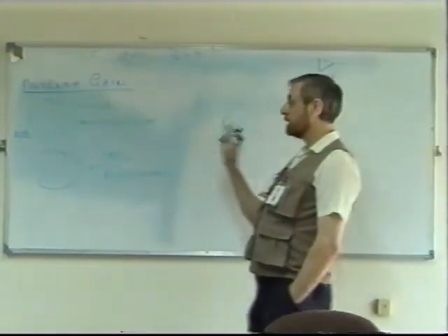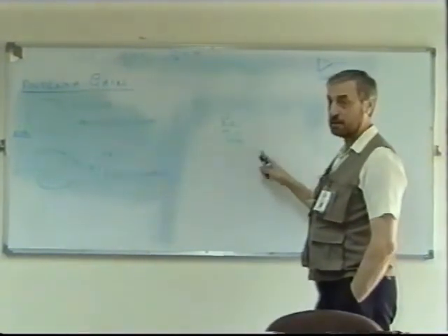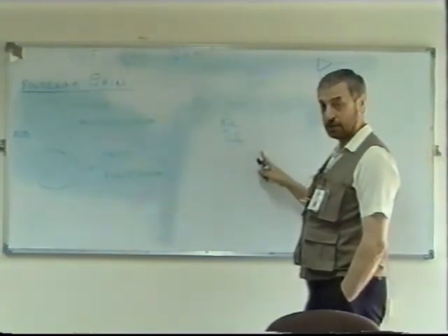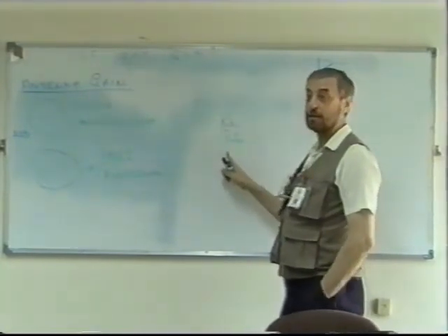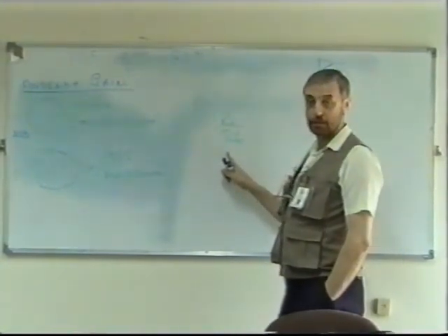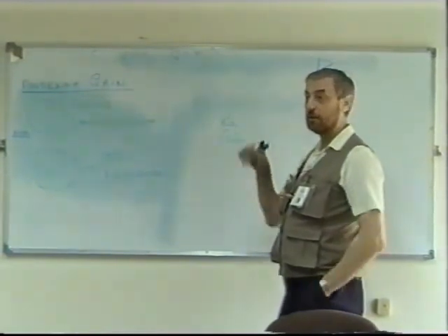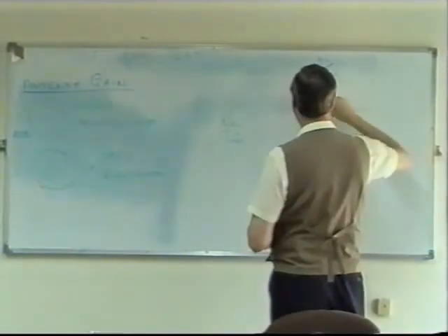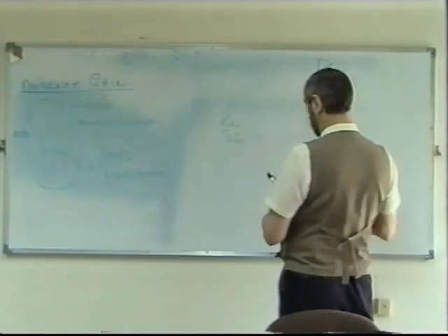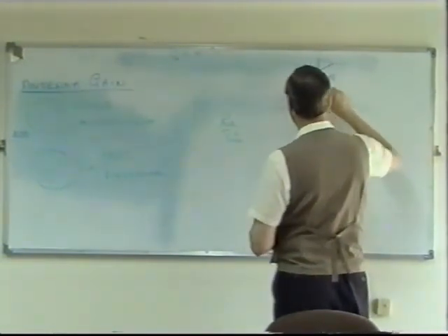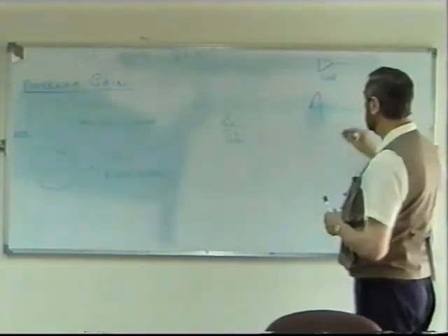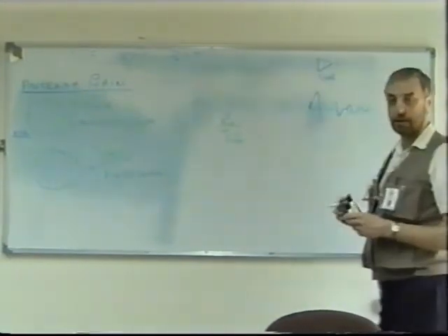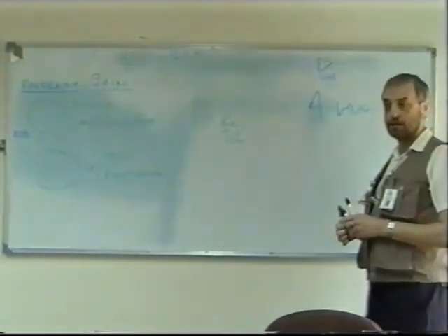Yes. So what I'm saying is, the further away I make the receiver, the less the signal strength is at the receiver. But of course the noise generated is going to be the same. So eventually the signal is going to go below the level of the noise. Remember, if we draw a graph here, and in green I represent this as the noise, now my transmitted signal should be above the level of the noise, shouldn't it? So we can receive it. Yes. But what happens as I go further and further away, this signal gets less and less, and eventually could be below the level of the noise and basically lost.